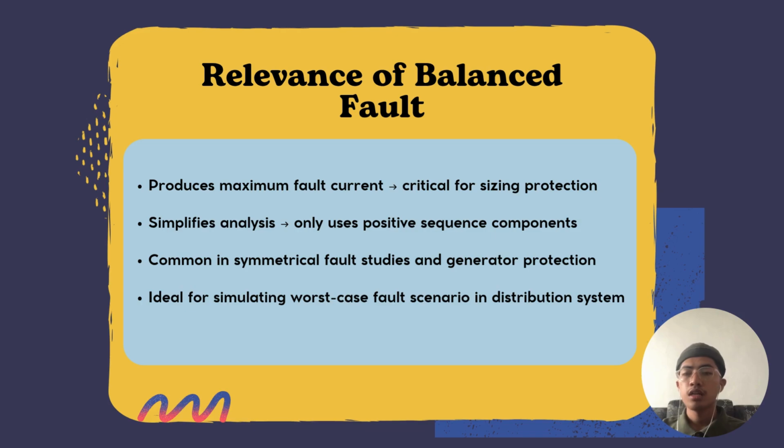Next is relevance of balanced fault. We choose to simulate a balanced fault because it represents the worst case scenario in terms of fault current. It's useful for designing and testing protection systems such as relays and breakers. Unlike unbalanced faults, balanced faults only require positive sequence analysis, which makes the modeling process simpler and more efficient, especially in simulation tools like Simulink.